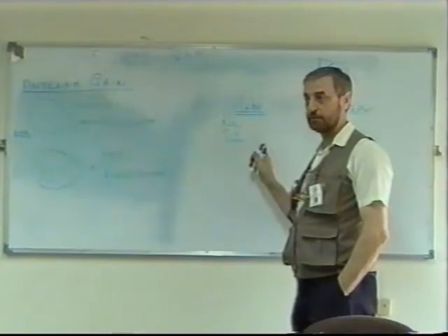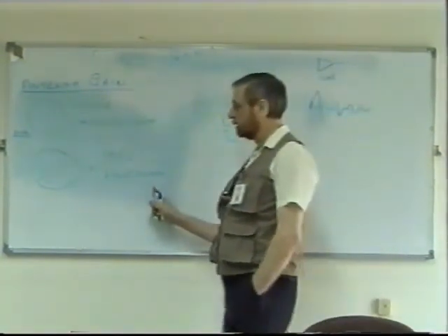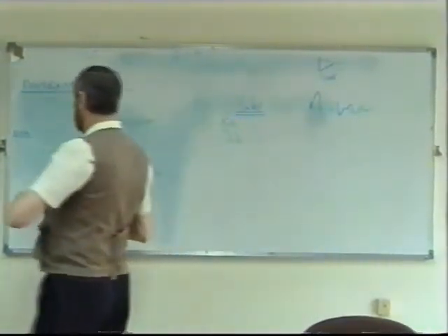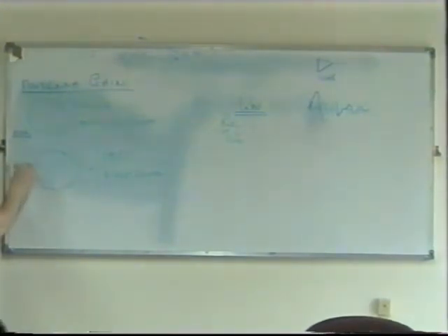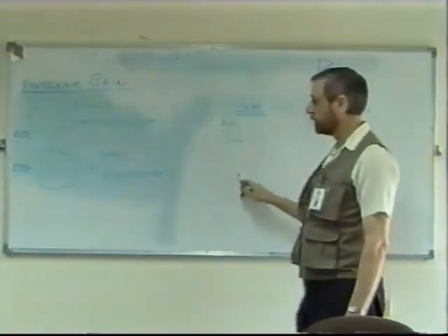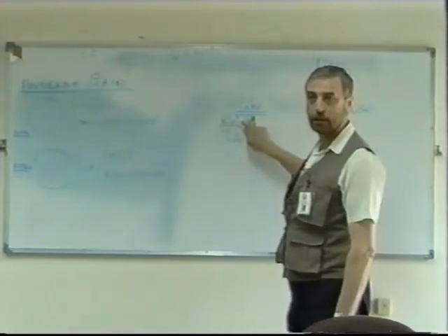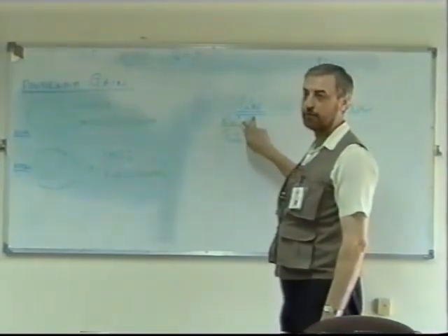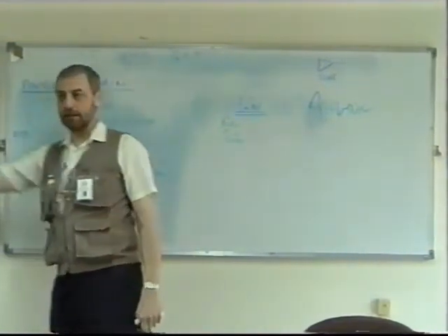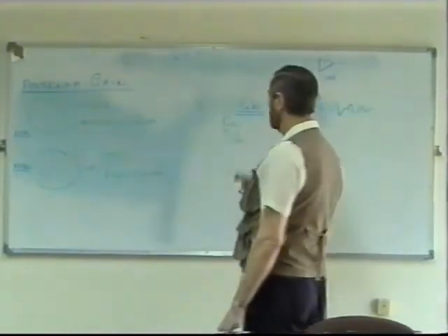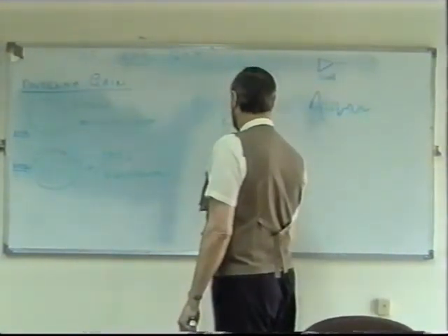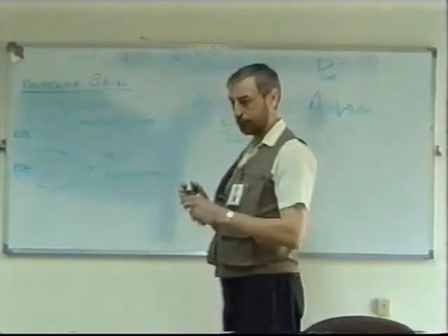in your receiver. Now if we take a Yagi, which is a directional antenna, so this is a different situation. What do you think, if I apply the same power here to the Yagi, and I put my receiver in front of the Yagi in the same direction, do you think I'm going to get 1 microwatt or more than 1 microwatt? More. Yeah, indeed we are. It seems obvious that we're not wasting energy, too much energy anyway, radiating in the backwards direction. Most of it's going to come forward, so we would expect a higher power here. Let's say instead of 1 microwatt, I got 2 microwatts. Do you agree with that?